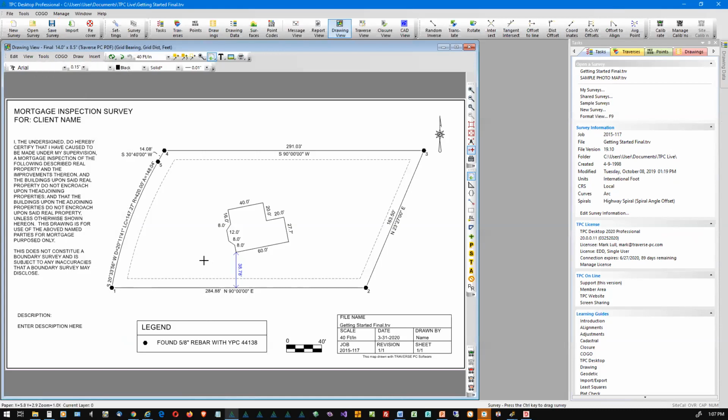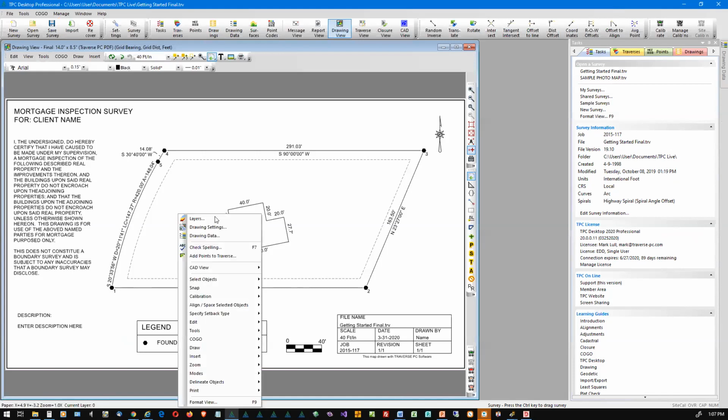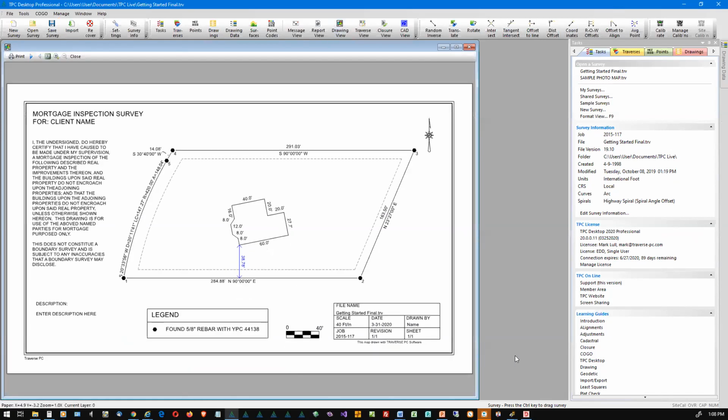What we have here in the drawing, this is what computer geeks know as WYSIWYG. What you see is what you get. And what that means is what I'm looking at on this drawing here is how it will end up printing. If I want to see how that works, I could come, once again, more than one way. I can right-click the background of the drawing, come to Tools, Print, and I can do a print preview. And now I can see exactly how this drawing will print.